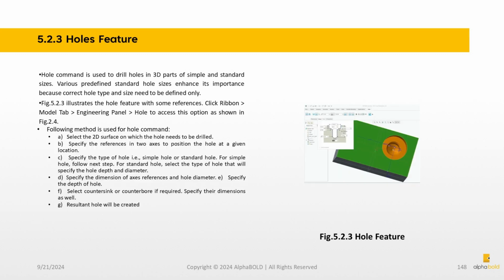Hole command is used to drill holes in 3D parts of simple and standard sizes. Various predefined standard hole sizes enhance its importance because only the correct hole type and size need to be defined. Click Ribbon Model tab, Engineering panel, Hole to access this option. The following method is used for hole command.